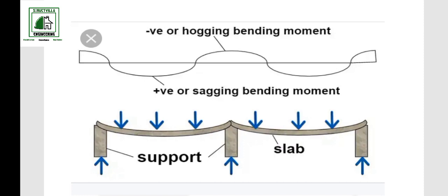So now reinforcing the bottom bars, you will notice that towards the support, there's no moment at the bottom bar. The moment there is almost zero. We just have top moment, moment for top bars, close to the support. But for the bottom side, notice there's no moment. But towards the midpoint of the beam, there's a moment there. That particular region is the positive or sagging bending moment. Notice that curve. That is the bending moment diagram for the center of that slab, right?